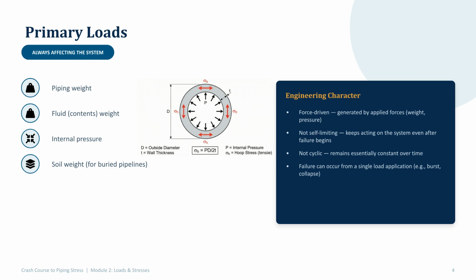Now, here's what makes primary loads special, and this is worth really understanding. First, they're force-driven. That means they come from an actual force, a weight pressing down, a pressure pushing out. It's not caused by something bending or moving. It's a direct push or pull.